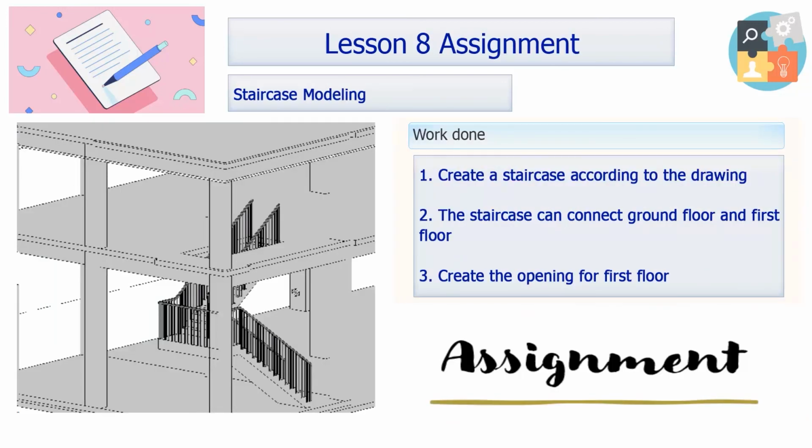For the assignment, please use the same skills and create another staircase by yourself. Create a staircase according to the floor plans. The staircase can connect the ground floor and first floor with a suitable offset. The opening should be created on first floor according to the drawing.